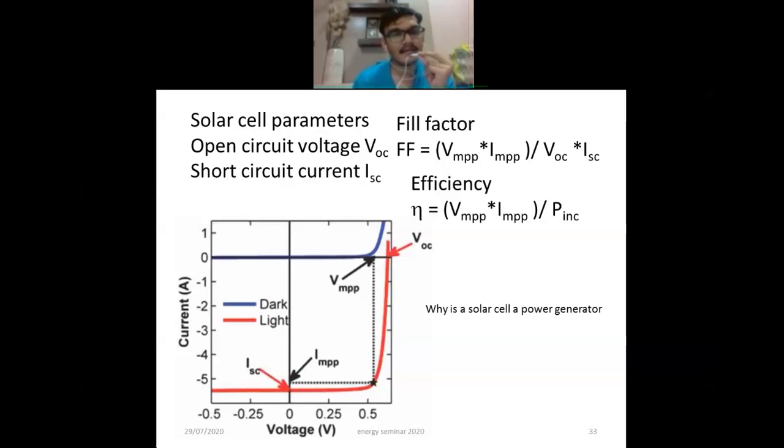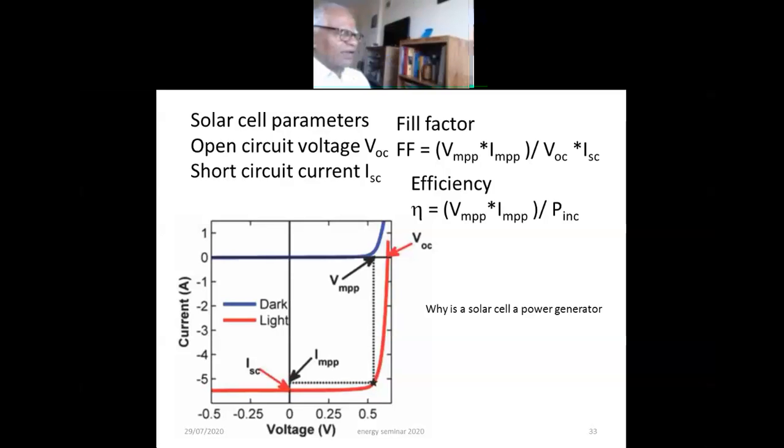No, because it depends on what my failure rate is. So for instance, in a real life situation, panels can degrade due to many reasons. One is, of course, if the cell itself degrades and the lifetime of the excess carrier goes down. But panels also degrade because there are metal grids and the connecting grid comes off, or the metal contact comes off.